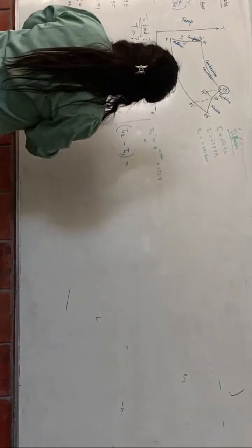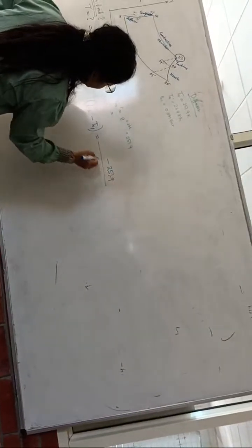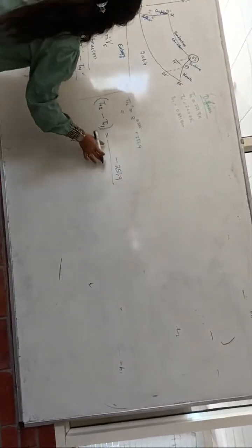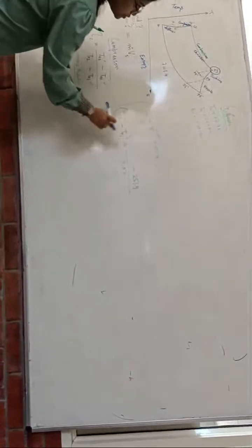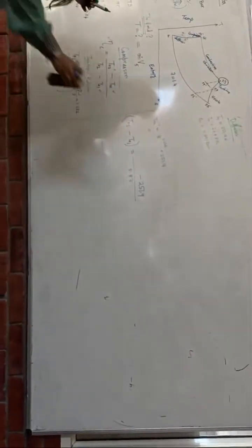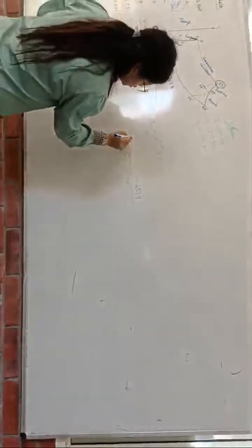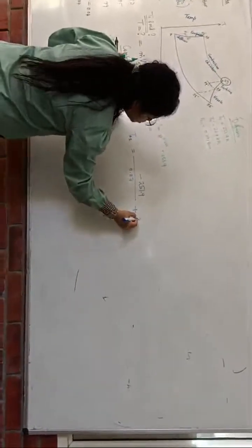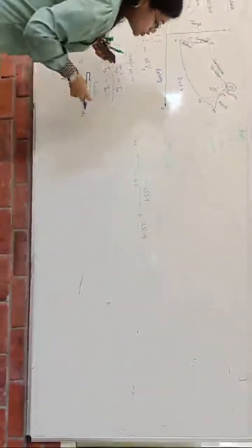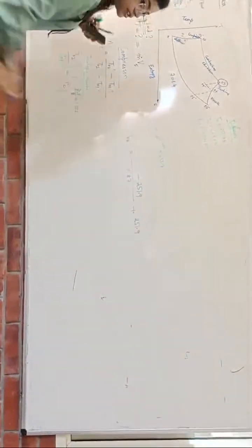So the value of T02 will be here, and minus T01, 251.9, divided by the efficiency, that value is 0.87. This value is also known to us, so I can take it to the other side. I'm just simplifying it over here. T02, the minus, so total plus of T01, that is 251.9 again. So once you find this T02 prime, that value will become here, so we can find this T02.